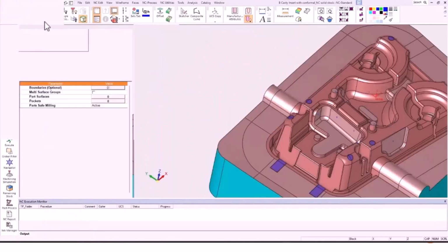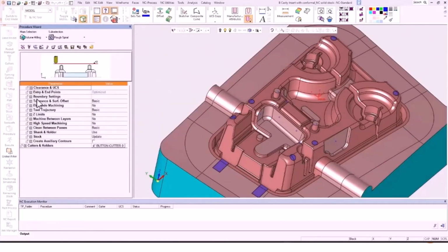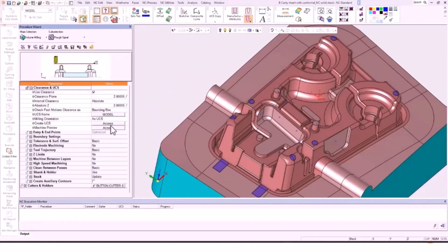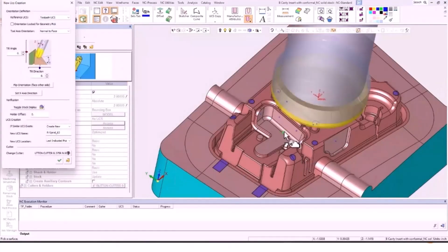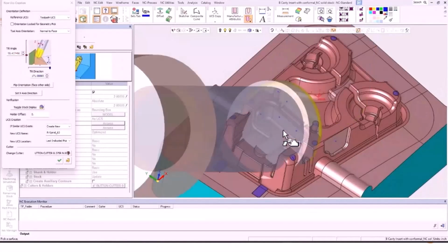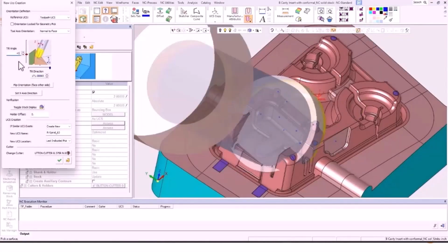or use by NC Tool here at the top. I'll choose the option to create a UCS from the procedure, pick the point I want to use, dial in the angle I think that I want to use. At this point, I also want to consider what the x-axis is. So I'm going to set the x-axis direction.